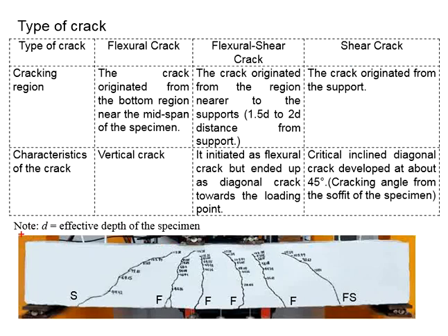There is a reason why it is so. You can imagine in this manner. You have a beam here. When subjected to the load here, the beam tends to deflect. Now the soffit of the beam is undergoing tension, while the top part of the beam will undergo compression. The flexural tensile stress will be the highest at the soffit of the midspan.